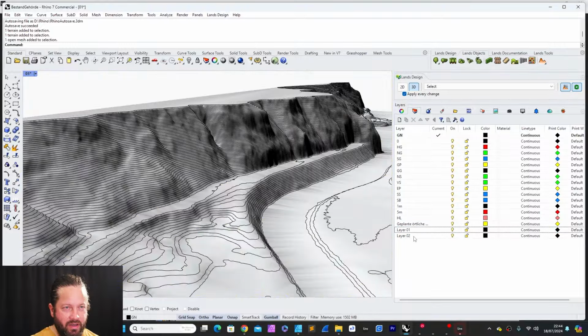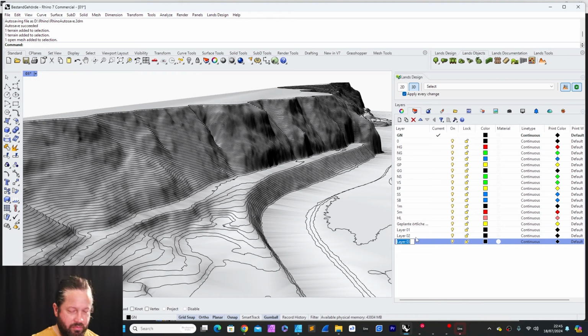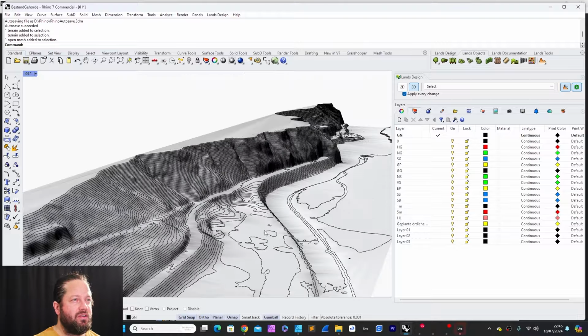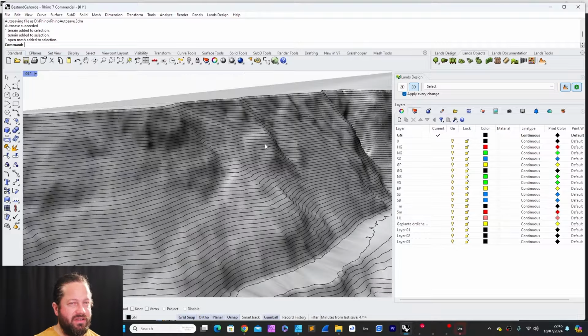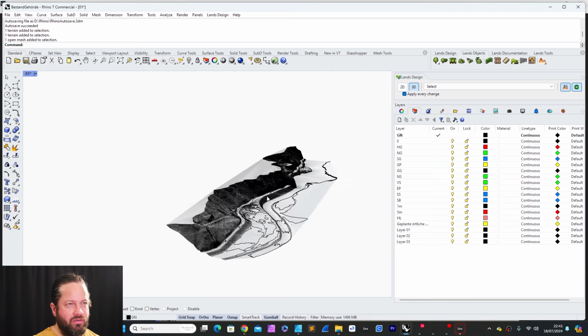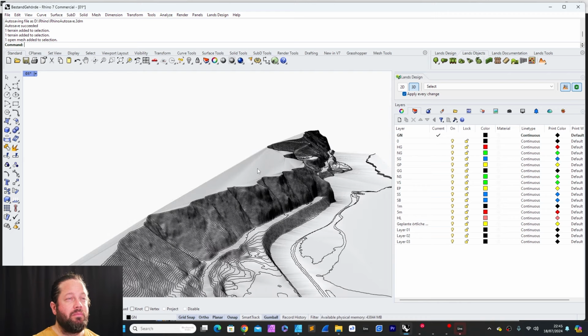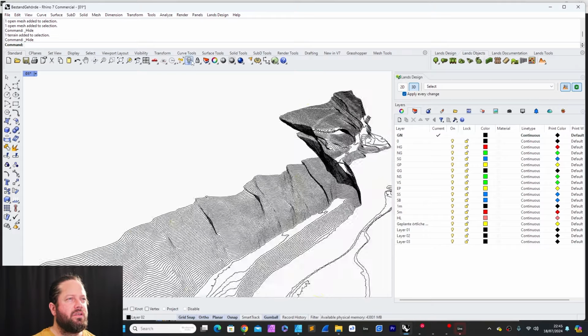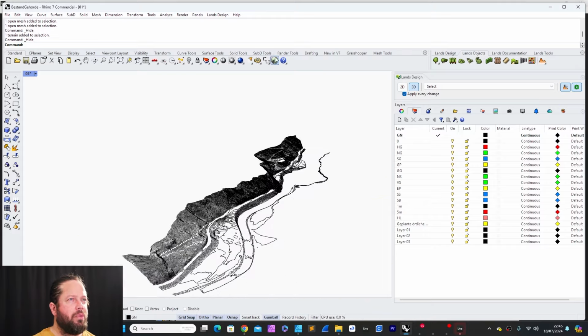Now, the other way, so I show you a third way to do this. This is a bit more elaborate, but it's useful if your contour lines are not polylines and you need to decide where your control points are. You can still use the control points, of course, but sometimes you want to be able to control the resolution of your outputted mesh. And just hide this again. I go back into Grasshopper.